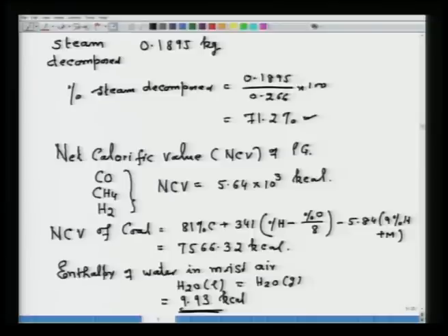Now, we are supplying steam also. So, another input you require is the enthalpy of saturated steam. For that you have to see the steam table, and the relevant values I am giving here. Our gas pressure is 30.8 psi, that is given.